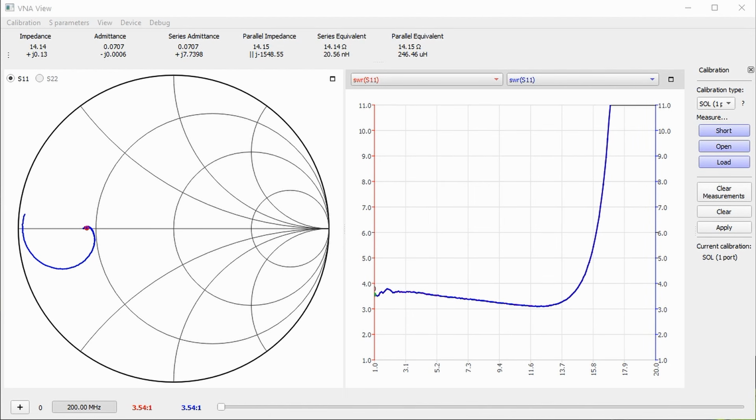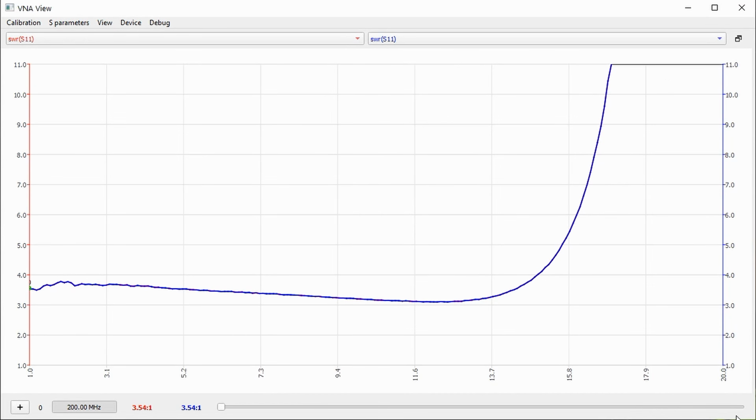As seen before, we can also check the quality of the match by looking at the SWR curve. It shows the distance to the sweet spot. And really, it is very flat up to about 15 MHz. Then it increases rapidly because the distance gets bigger and bigger. At the sweet spot, the SWR would be 1. Now it is around 3, a bad match. You see, we do not need a Smith chart to just know if an antenna is good or bad. The SWR is sufficient for that purpose. When do we use the Smith chart?